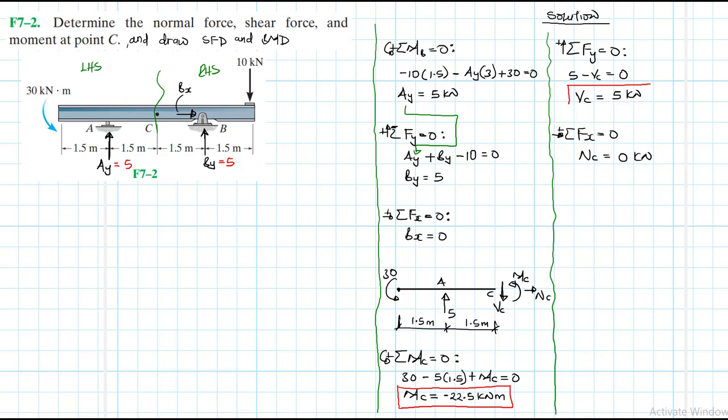Then we have the shear force. Okay. Then we have the normal force. Right. So like I said, we are going to draw the shear force and the bending moment diagram. And we are just going to use the differential equations that relate the distributed load to the shear to the moment. So we know that the rate of change of moment with respect to x